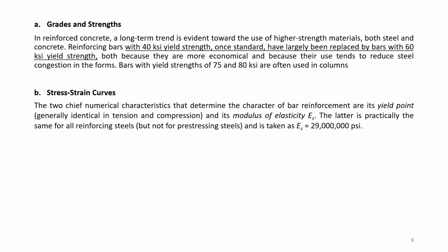Nowadays 60 KSI steel is preferred, and 50 KSI steel is not available, and in very small structures, 40 KSI steel can be used, and up to 70, 75. Nowadays in Bangladesh, there is a grade 72 that comes from the MKS system. That's why it is 72. Otherwise, in the FPS system, the grades are 40, 50, 60, 70, like that.